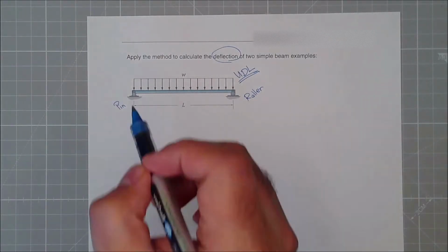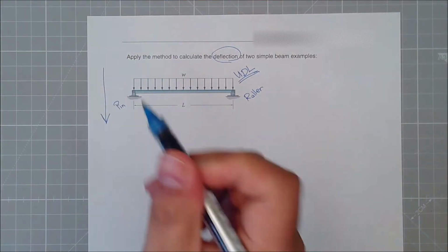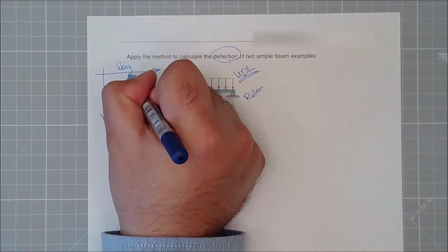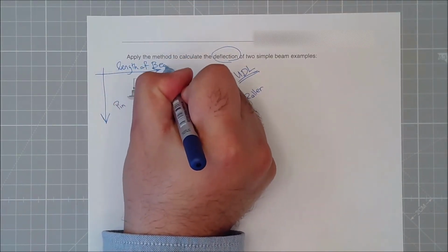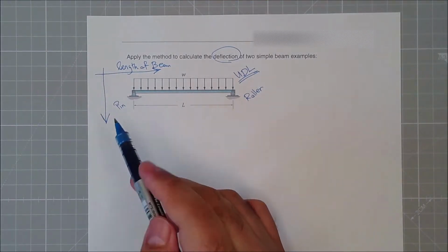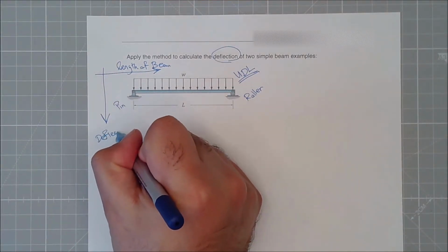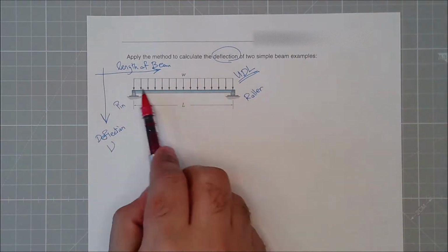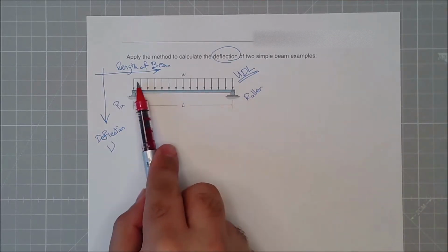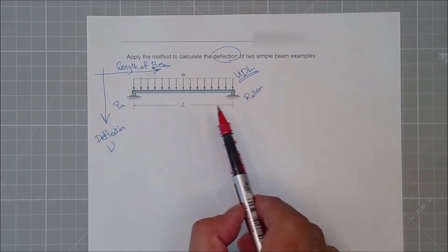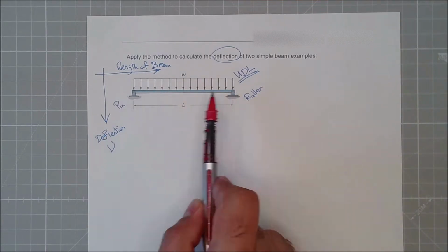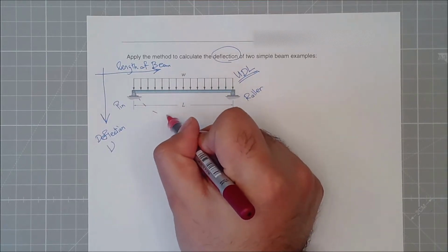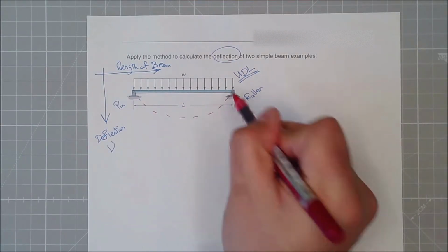So as a method, I'll draw two axes. One of them will be the length of the beam, which as you can see is L. The other one is deflection. And I'm sure you can all guess that if such a uniformly distributed load, for example an elephant sleeping on this beam, is applied to this beam with these support conditions, the deformed shape, the deflection, will look something similar to this, very symmetric as well.